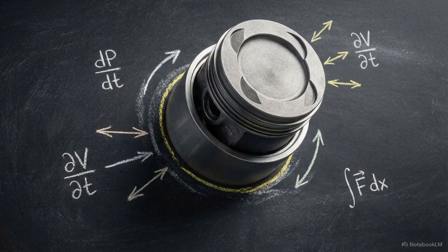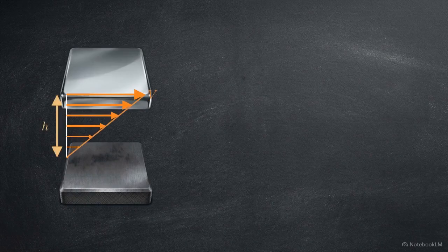In mechanical design, the fluid spaces we evaluate most often, like the microscopic gaps between engine parts and lubricated bearings, are incredibly thin. Because the fluid film is so thin, engineers bypass complex calculus by assuming the curved velocity profile is a straight line. The differential terms du and dy are replaced entirely by simple algebra, the total velocity v divided by the total gap thickness h.